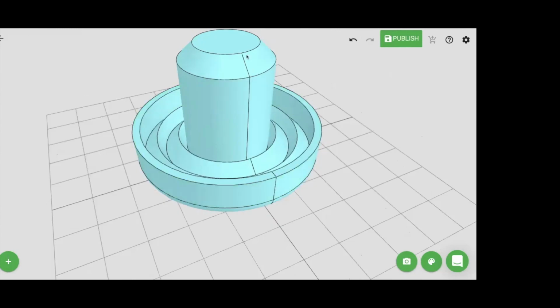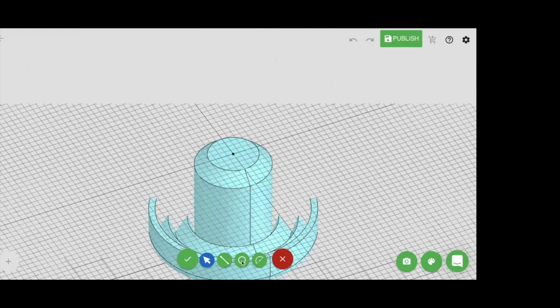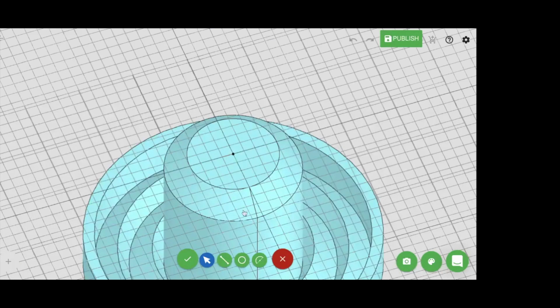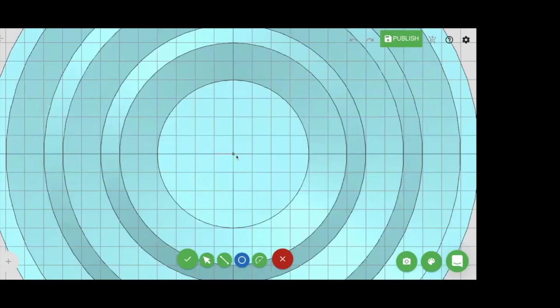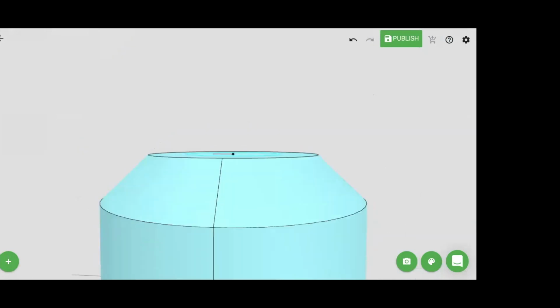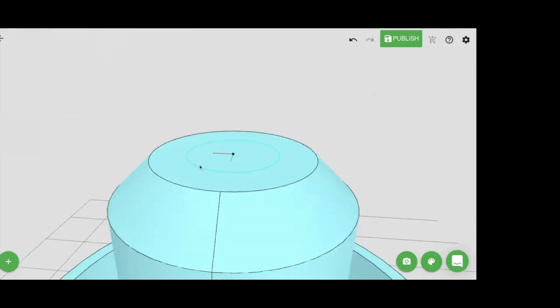And if you get too fancy, some complex shapes are sometimes going to break or give you an error, but for the most part, if I wanted to cut a hole through this bottom all the way through, I could just sketch. Here, I'll just do that. Hopefully, because I'm streaming, and again, this is an old 2011 Mac on a Brave browser, I mean, this is like pushing it, running on this. But all right, so I just drew a circle, and now I'm going to do something fancy where I actually just double click the part, and then I hold Command or Control and single click the sketch, and so now I've got both connected.